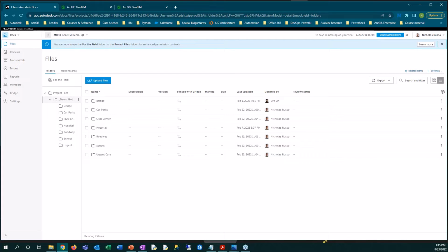With that said, there are a few high-level best practices that should always be followed when organizing data within ACC. First, make sure that you are creating a project for each real-world construction activity. You want to avoid at all costs catch-all type projects where data can get confused, and this can open the door to outdated or bad data being applied to decision making.